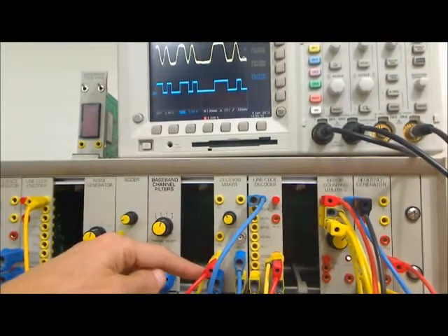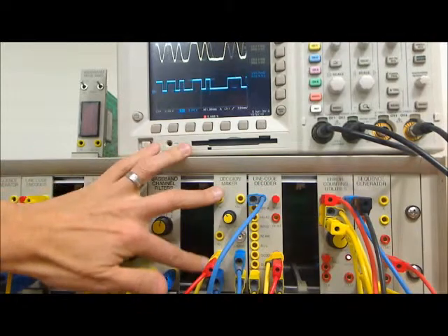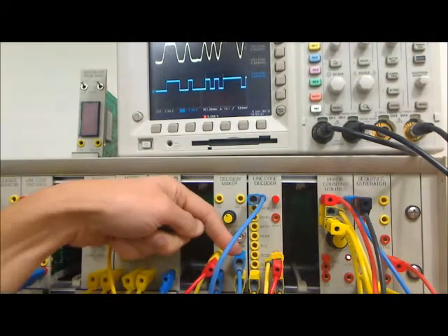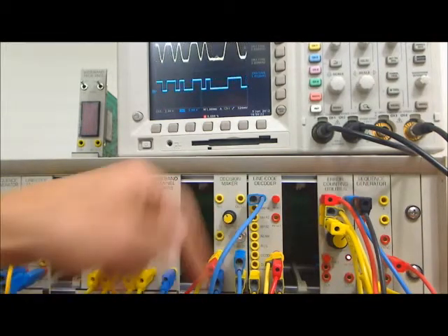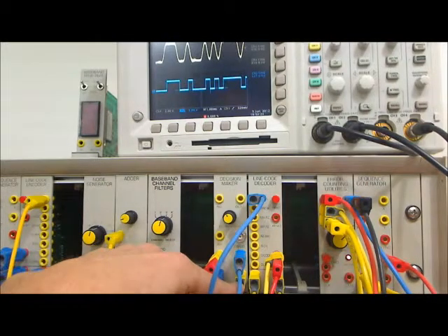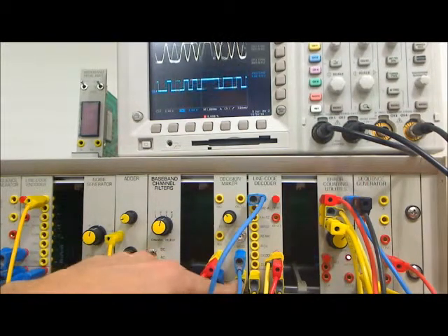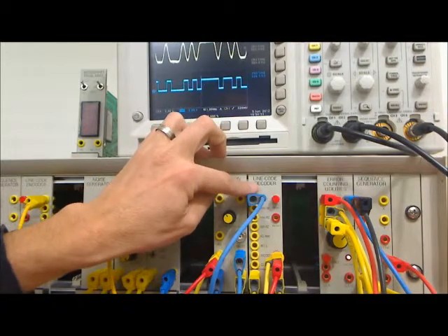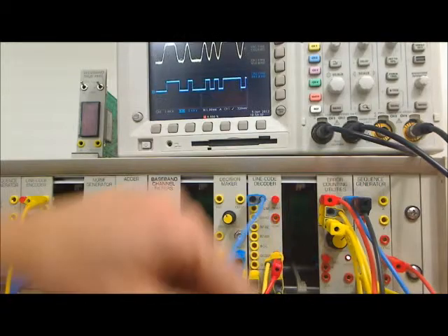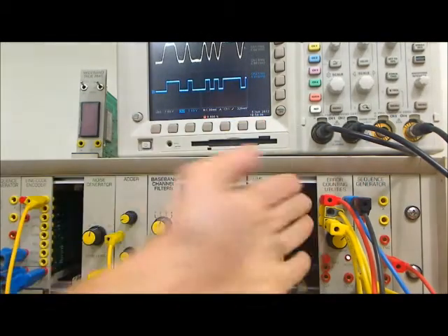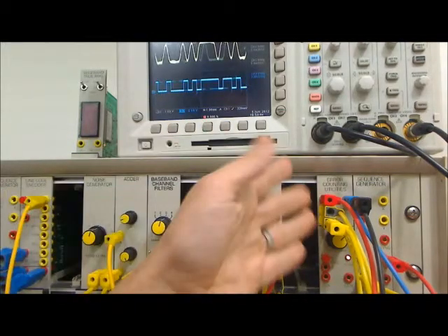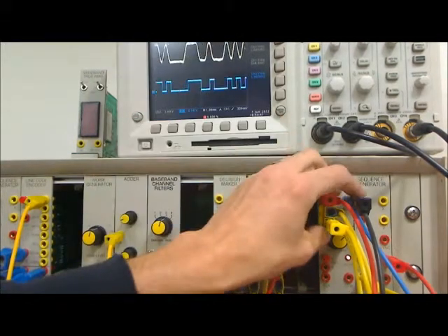Just taking a step back, look at these clocks. The decision maker makes a decision, and as well as outputting the sampled signal, it outputs an appropriately phased bit clock. This clock is fed to the line code decoder, which also outputs its own phase clock, which is then passed to the error counting utilities. So now we're operating with a local aligned clock which is aligned to the data.